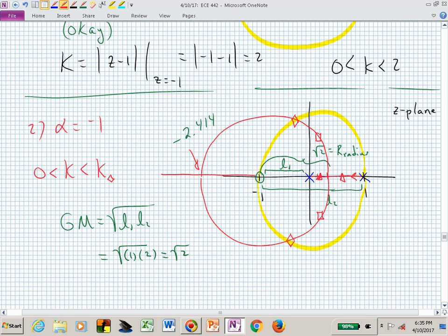But now if I have closed loop poles at the triangle, I have settling time spec only. Percent overshoot, 0. Peak time, 0, or I have 0 peak. What about at the squares? Now I do have percent overshoot. I do have a peak time because they're complex roots. And that's because I cranked up my gain k a little bit more to get me to the square. And that's why you're going to be paid the big bucks, because you're going to know how to tweak that gain and how to pick the alpha.